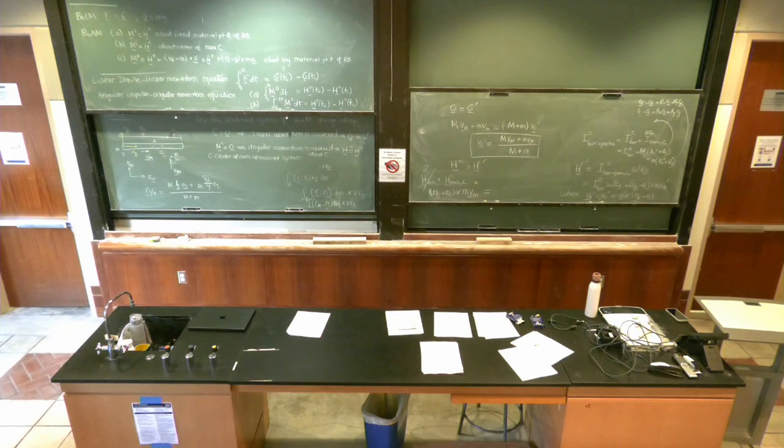So the way you find the center of mass here is you just treat some point as your origin. Yeah, I think I treated point A as my origin. And then you have to do algebra. Yeah, that's fine. Then if you treat A as your origin, your center of mass would be at small m times L over 4 divided by small m plus big M. Yeah, and so that would now be my r_C.